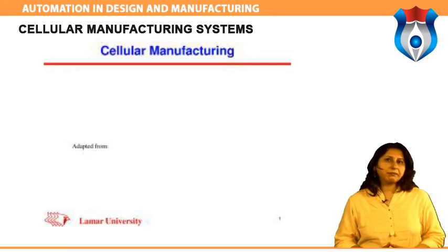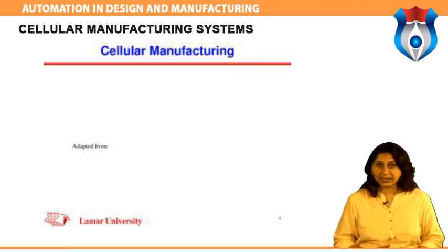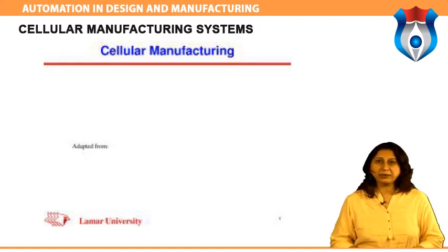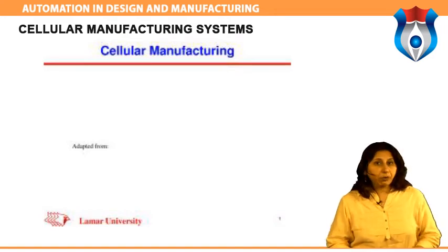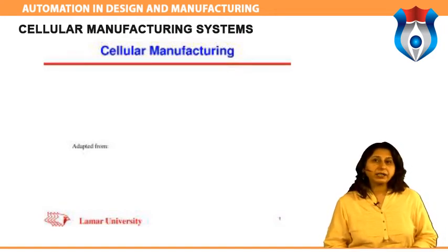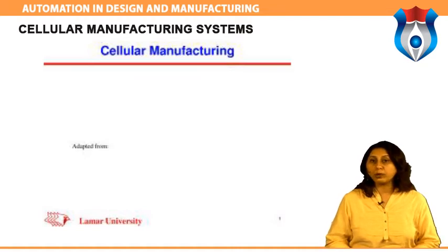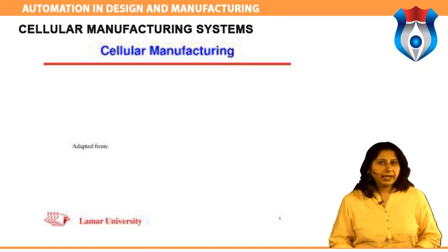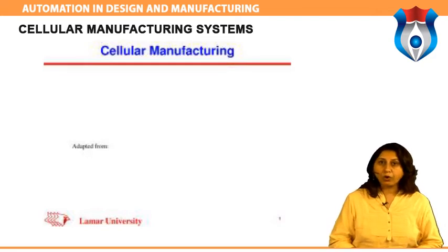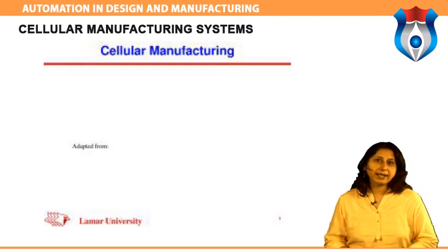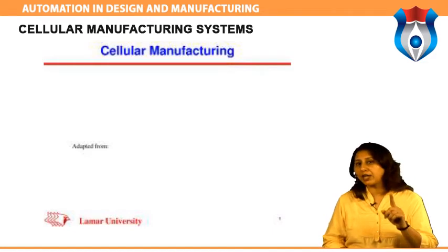It is not enough to simply arrange different equipment in sequence to make cellular manufacturing really work. Bottlenecks along the single process flow must be eliminated, usually by balancing the equipment capacities with each other. If bottlenecks exist, then the higher capacity equipment within the line will be underutilized. Balancing equipment capacities may mean choosing right-sized equipment that match each other and/or combining two or more small capacity equipment to match one large capacity equipment.